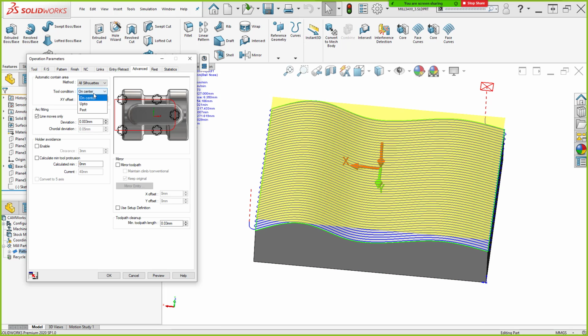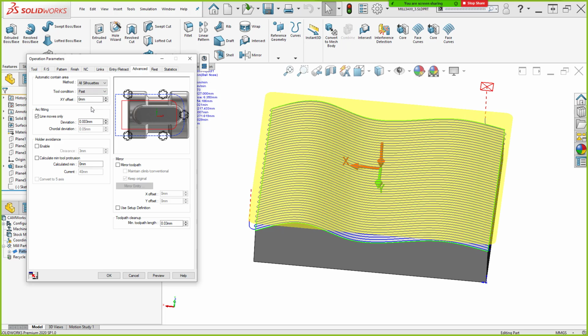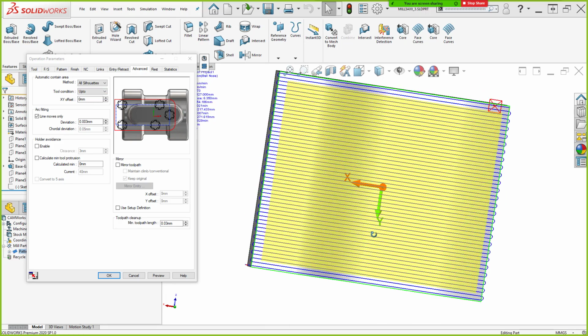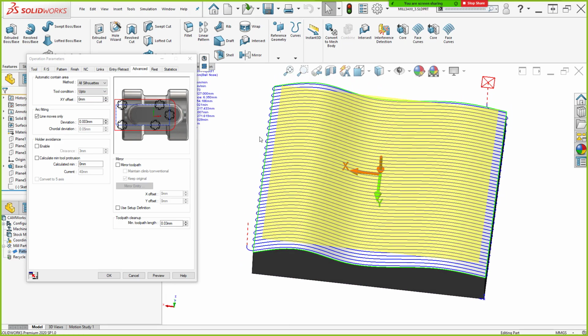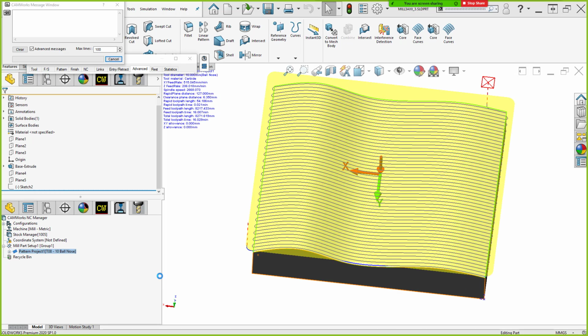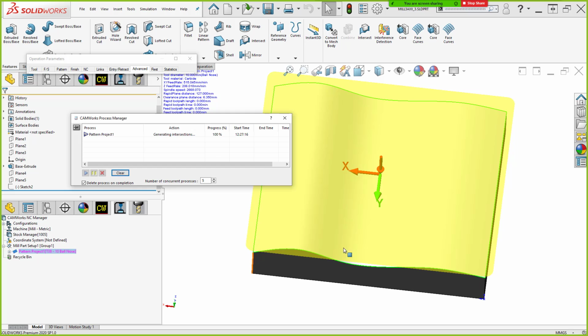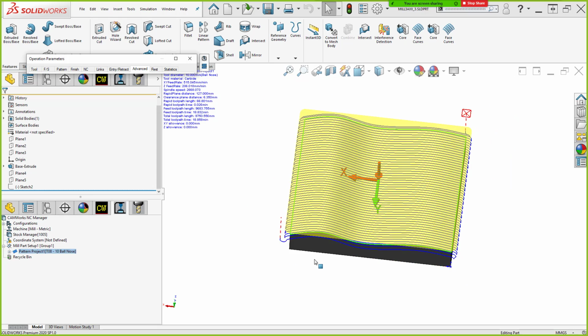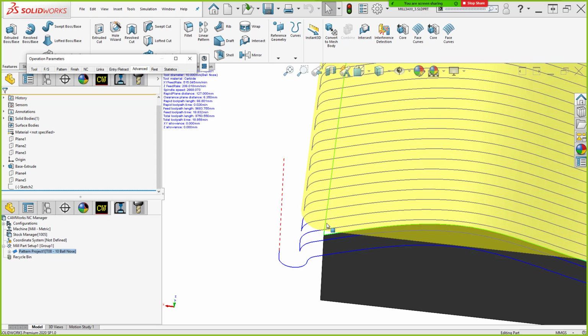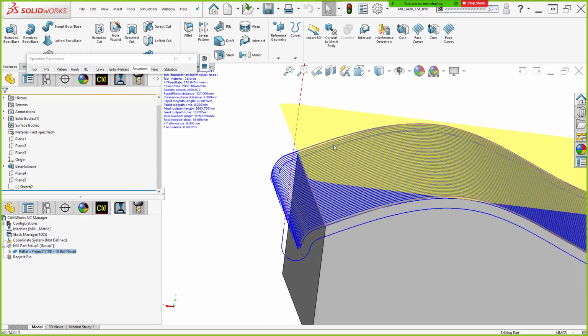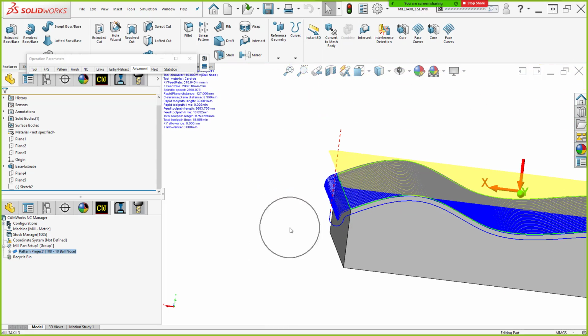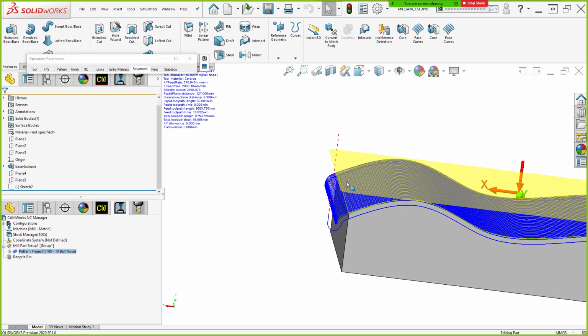But if I go in and say the tool is allowed to go past the contain area, I can even add offsets here, or up to, right? This would be more of a pocket condition, like stay within these edges, stay within the walls. But I can do past, for instance. I'm allowing the tool center to go past the silhouette, right? I'm increasing the silhouette, in other words. The tool doesn't go down quite as far as when the stock extents were used, but there's a little bit more wiggle room for it to spill over.